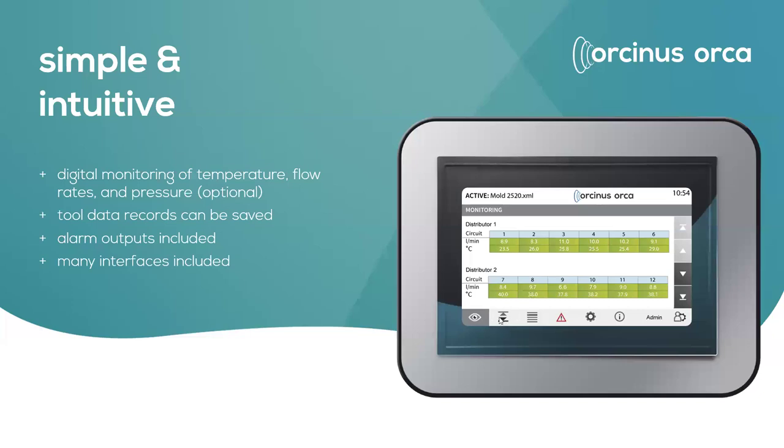Here, you can set your tolerance window. You know your process and you know which temperature you need to have a perfect quality of your parts. And you know the flow and temperature which make perfect parts, so you can define it. Here you can save the recipe for every single mold. So after a mold change, you just load the new recipe for the mold, in this case 2520, and then you will have all the numbers stored.